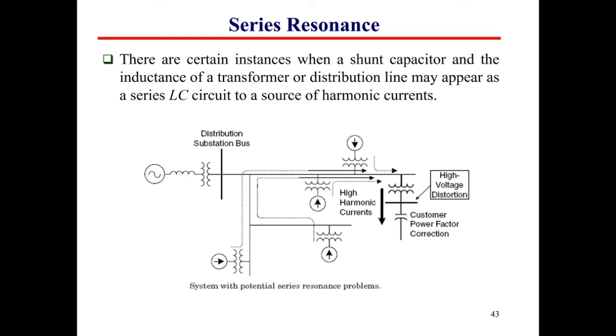Series resonance. There are certain instances when a shunt capacitor and the inductance of the transformer may appear as a series LC, like this one over here. Here we have the capacitor bank in series with the transformer, so that will make a series resonance for the harmonics.